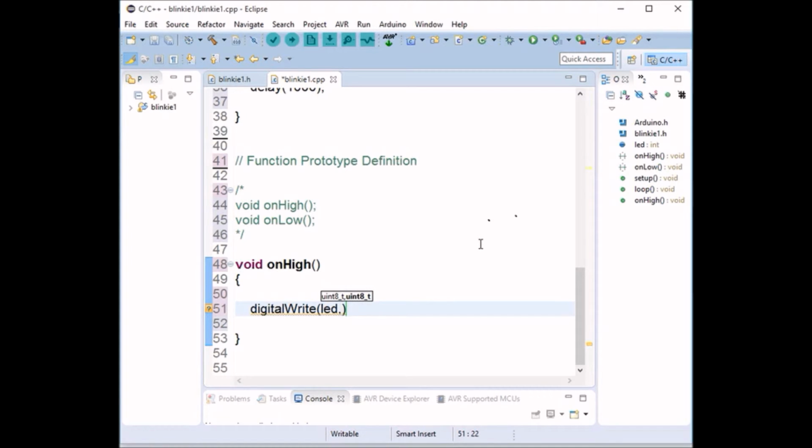I know it doesn't seem all that descriptive right now, but it's telling you that the function is taking two parameters. It's taking an int, which is going to be our LED, of course, our pin is going to be an LED. And it's also taking HIGH, which is going to be an int. It's just something you should know. It's going to be HIGH, and remember, that's all uppercase. Then you hit your tab, because when you see that little green line outside your parameters, that means you can hit tab and it's going to go outside of the parameter. See? Then you close it up with the semicolon. Okay, let's hit enter and go to our next part of the code.